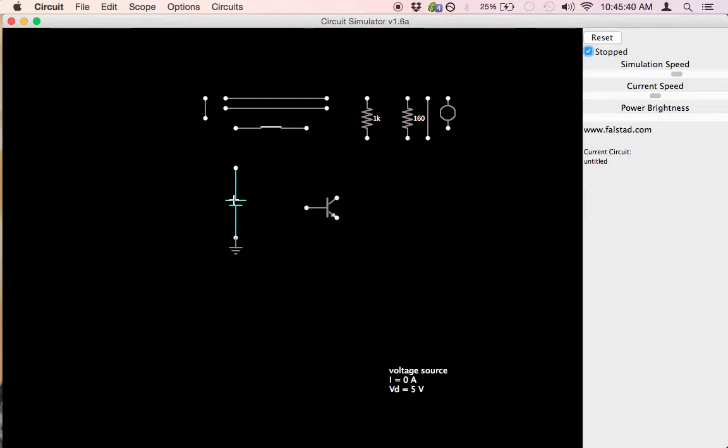I have here on the left a 5-volt power supply, and we're going to wire it up to this transistor. I'm going to use a switch so we can turn the control signal off and on. And I'm going to allow the current to return from the emitter. Got some small wires here. And I've got some components already picked out. I've chosen these components based on the voltage of my power supply, the requirements of the transistor, and the current that we're ultimately going to control, which is a LED current.